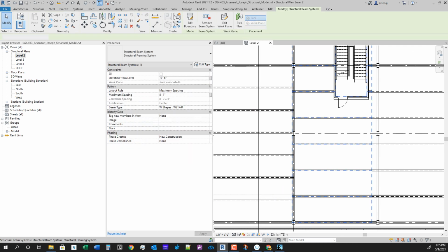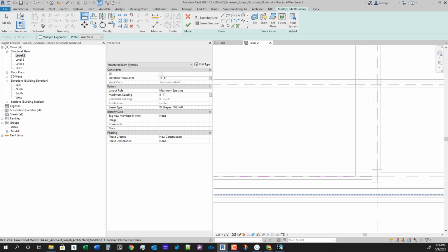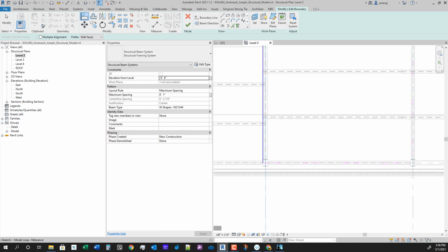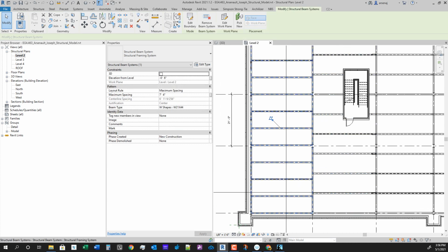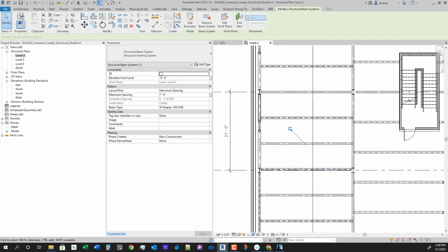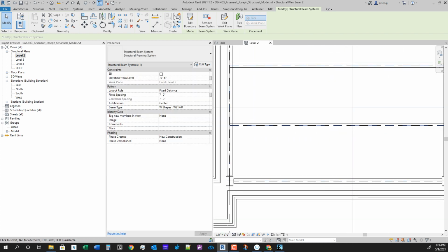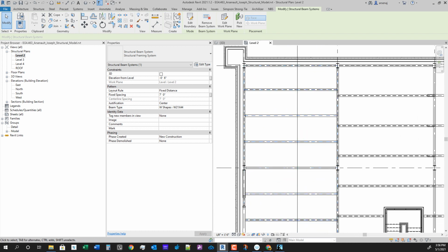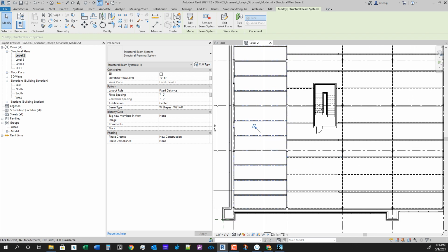Let's move to our next one and adjust our layout boundary. And so what do we figure on here? 7'4". So if I did a fixed distance, 7 feet, I think let's do that. That seems like that's perfect because what it's doing is it'll start this fixed distance and it's landing right centered on here. So let's do that.